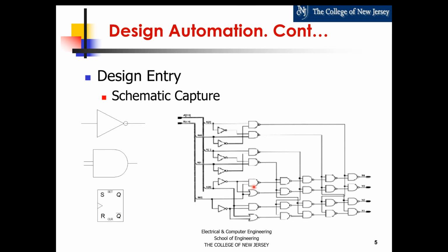So schematics can get cumbersome very quickly. I mean, this is just some combinational logic with a few gates, and already it would take a few minutes to put this together and to hook up everything and to instantiate the gates and plop them in the canvas and draw the lines and things like that.